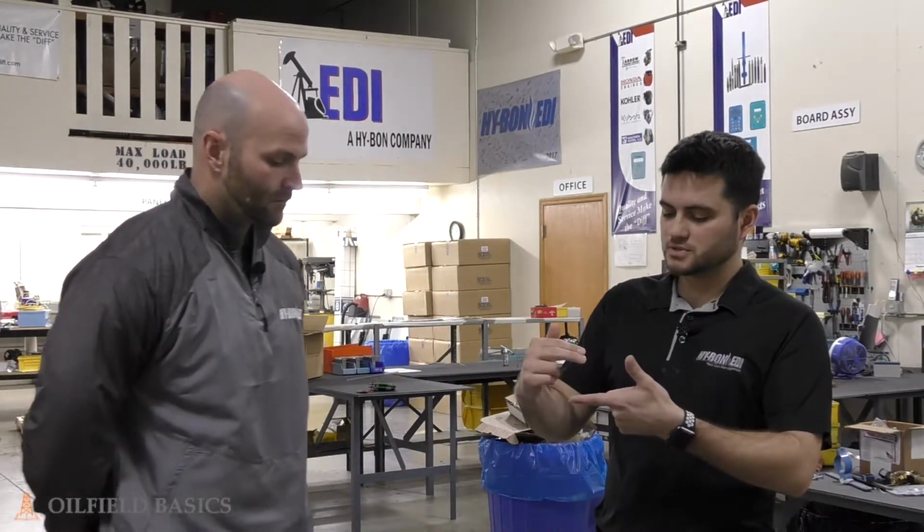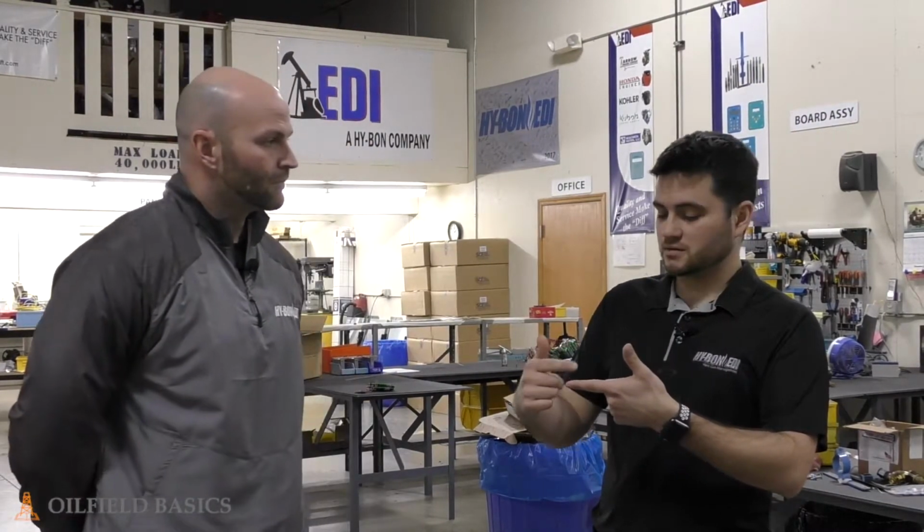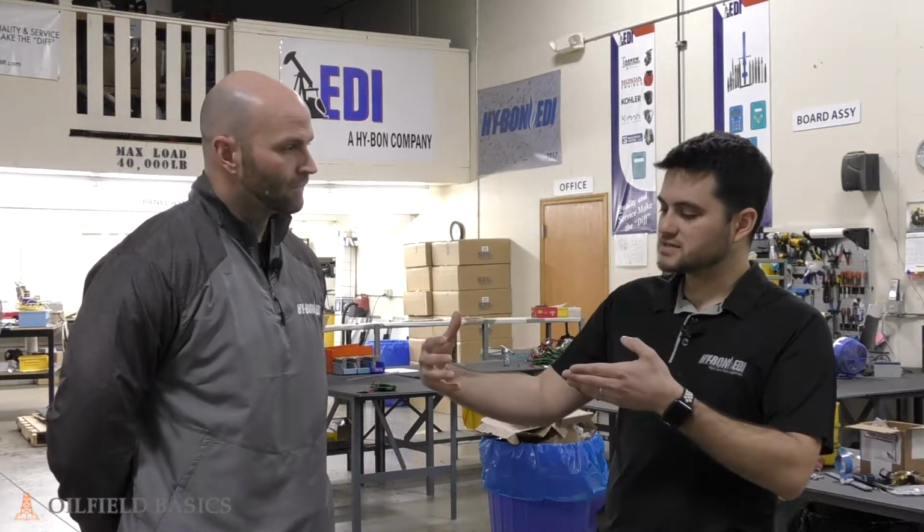But the way that the flame arrestor works is that there's crimped sheet metal inside of there, very thin, very light, sometimes aluminum. It increases its surface area by being crimped in a circular fashion. And as that flame propagates backwards, it acts like a very efficient heat sink. It's pulling that heat away from the flame so it can't keep going backwards. The minimum ignition temperature has been removed because it's absorbing all of that heat so effectively.